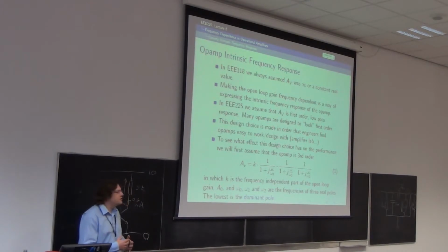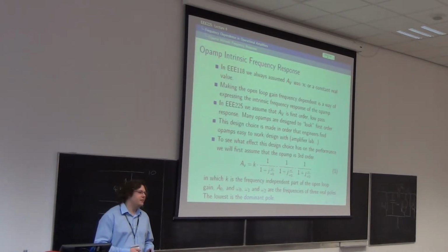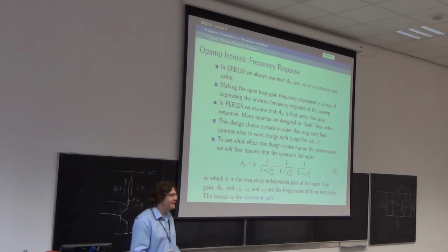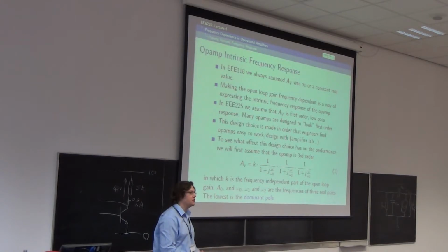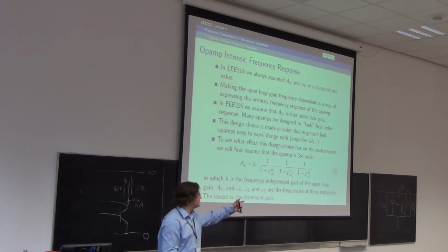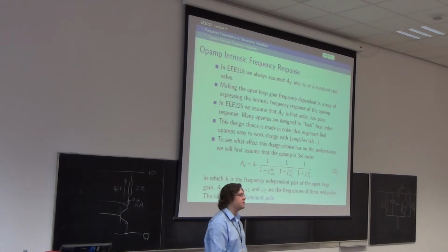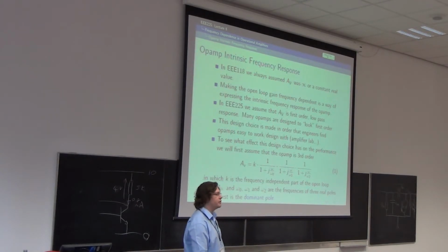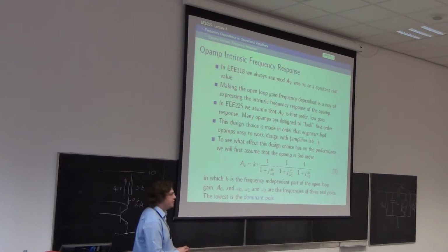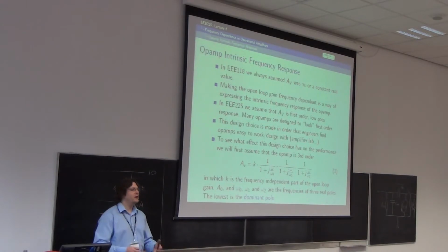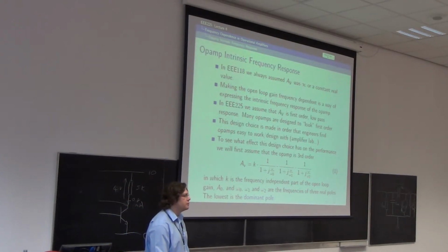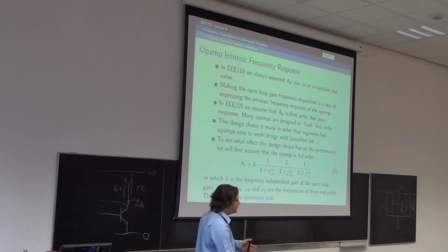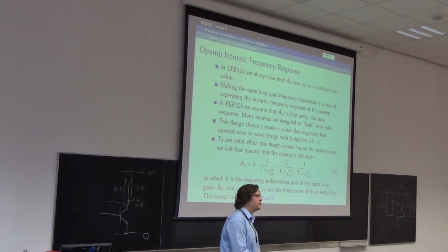And we will say that it's first order. Now, it's not really first order. It's quite high order, and if you look at the number of transistors dotted about the diagrams on the earlier slides, you can see if all of them have two frequency-dependent components attached, the order is going to go up pretty fast. But usually we can say op-amps are about third order-ish, and most op-amps will be designed by the people who design the IC to look as if they're first order.